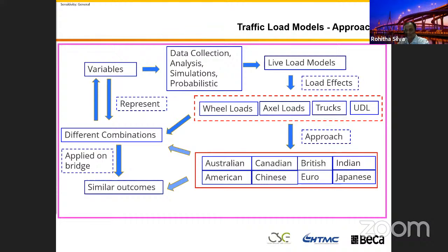No, you can't do that, right? In bridge design, you can't do that. If you select a particular design code, you have to adapt to that one. You have to follow all the design guidelines given in that code. The reason I need to emphasize this: if you select a particular code, for example, in Sri Lanka, you are using Eurocode. In Australia, we are using the Australian code.